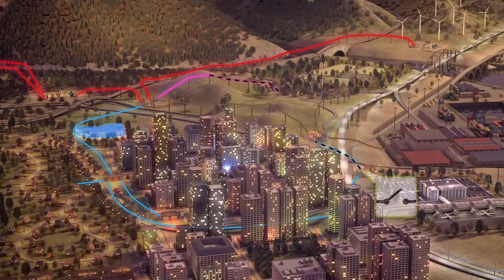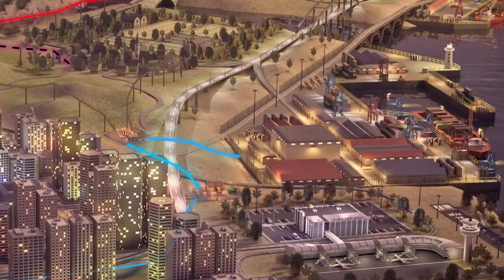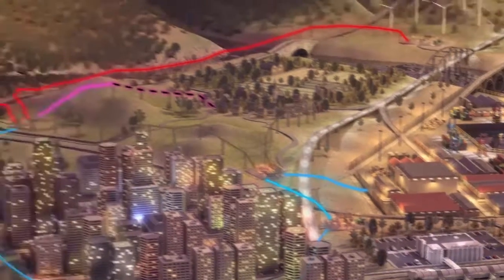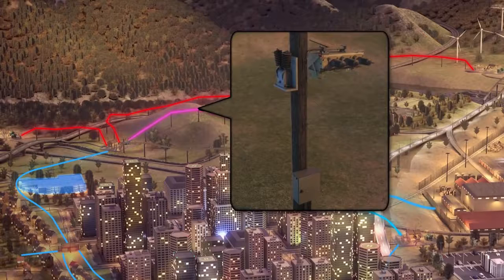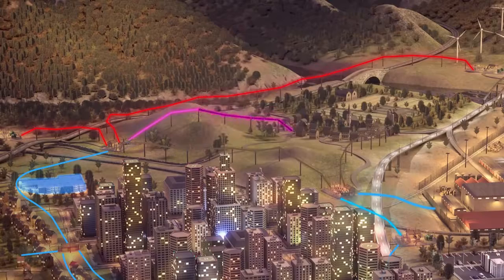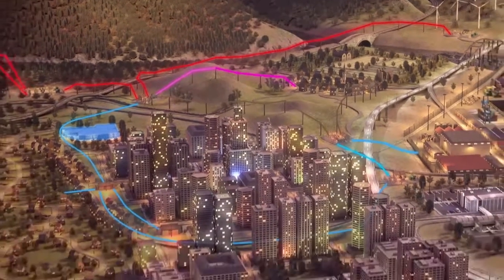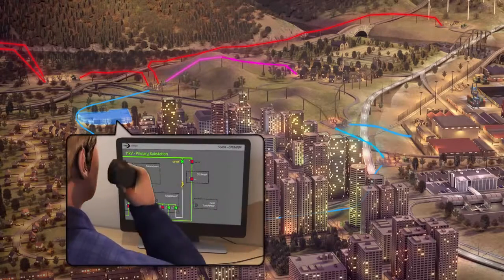The operator can now close the outgoing switch at substation 3 to re-energize the link to substation 2. Substation 2 can now reinstate the supply to the port. In order to avoid overloading one side of the network, the operator chooses instead to close the GX switch on the backfeed to the rural community to reinstate their supply. Supplies to all affected areas are now complete and the faulty line is safely isolated from the network, allowing the operator to arrange for a repair.